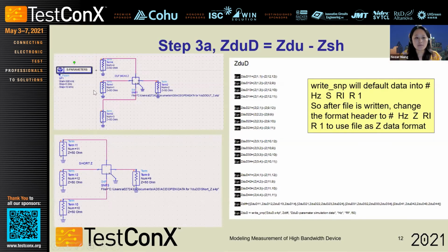In this step, you will see everything was exported to the ADS software, and then I simulated from 300 kilohertz to the gigahertz. This is just for generating the signal. And then I put in the measurement data here and change to the Z domain.